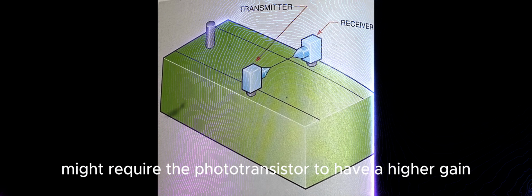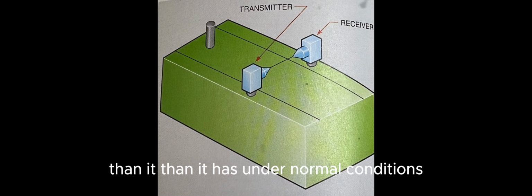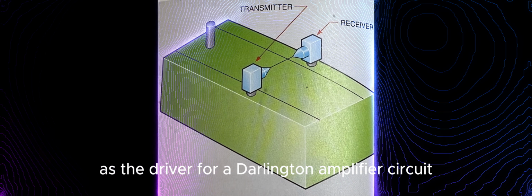Some circuits might require the phototransistor to have a higher gain than it has under normal conditions. This can be accomplished by using the phototransistor as the driver for a Darlington amplifier circuit. A Darlington amplifier circuit generally has a gain of over 10,000.